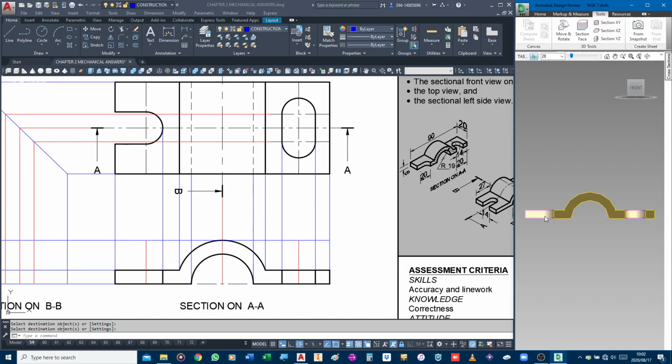Now, the important thing here is that I want to show you. Remember I said, let's look at this. That part there, a lot of people throw away because they think they're cutting through here and then they're not drawing those lines. But I've got to remember, there's still geometry that I can see behind the cutting plane. So, if I can explain it this way: if I look at this groove here, those lines will be solid.